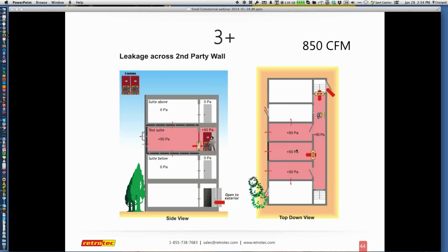What you want to make sure of is whether it is a building issue or a tenant issue, and keep in mind who's actually going to make the corrections or at least take care of your bill before you showed up. If they were upstairs or downstairs, you would do the same concept of pressurizing here, then going downstairs and pressurizing the unit below. Same thing as I would do next to it. So in theory, there would be one on the right, left, potentially above and below, all trying to subtract the CFM, so I could isolate where I found my greatest leaks or issues based upon multiple tests.